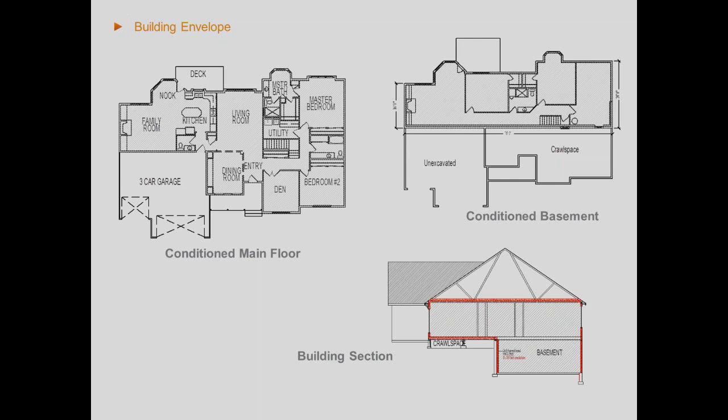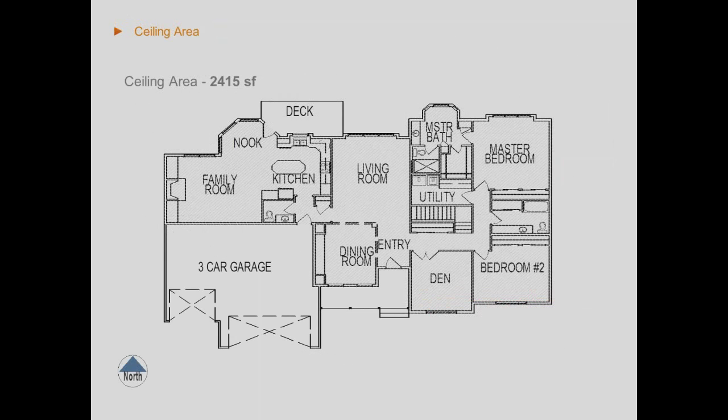If you lift that highlighter up, then you might want to be taking a look on your building plans of why. If you can do continuous highlighting around that building envelope, good, because it's required by code that you have a continuous air barrier. So this shows the building section for the main floor and the basement section.